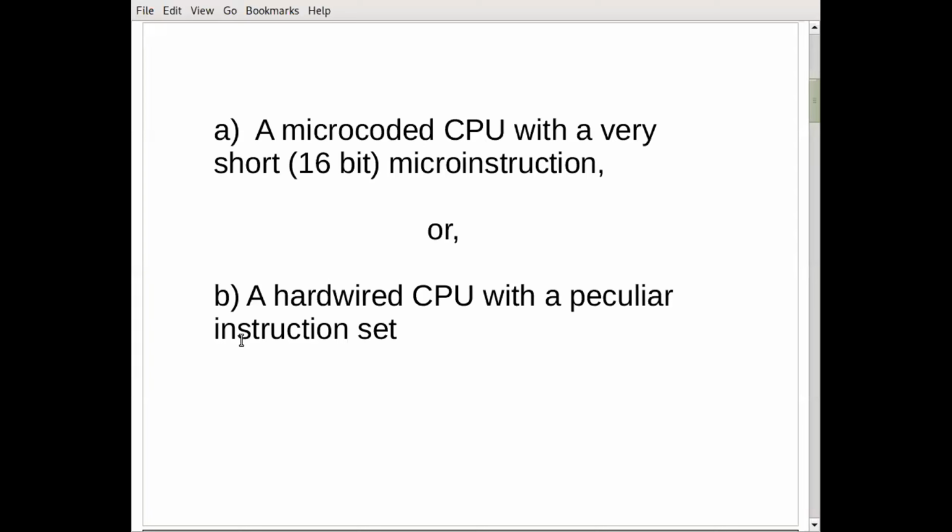So that led to calling it the pathetic instruction set computer, which is, I think, probably the most idiotic instruction set of any computer I've ever seen. It has no branch or conditional branch instruction, for example. It has no way to rotate or shift right. And it can shift left, but to rotate left, you need multiple instructions.